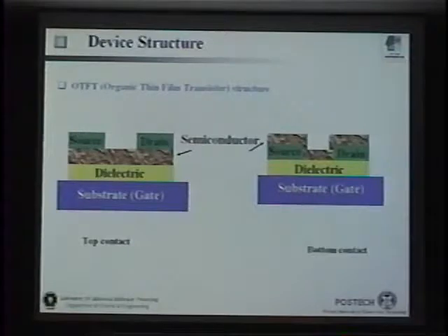And in this case, we have a contact between ITO, an inorganic oxide, and then pentacene organic molecules. So as Dr. Lee mentioned, we have all kinds of contact problems which degrade contact resistance and also transistor performance. Sometimes the insertion of a SAM layer helps this contact, and also the dielectric and semiconductor interfaces. So there are many ideas with different molecules to deposit by self-assembly to improve the interface properties.